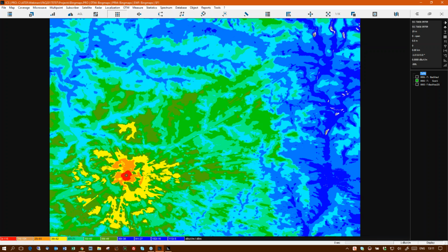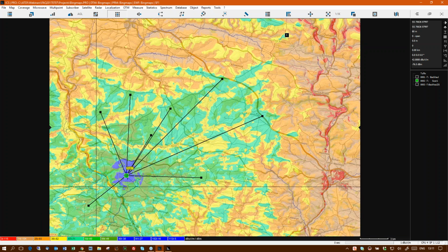We'll just finish that. So that's the coverage plot, and as you can see, all the outstations are nicely covered by this base station, not a lot in between. But for point to multipoint, generally speaking, you don't do coverage plots. It's not really necessary. It's multiple fixed links, and you're really dealing with path loss between these 2 points, and you're not really interested in whether or not there's any coverage in between, unless you've got a lot of points and you just want to get a feel for the kind of coverage that base station has got. Generally speaking, coverage isn't necessary.